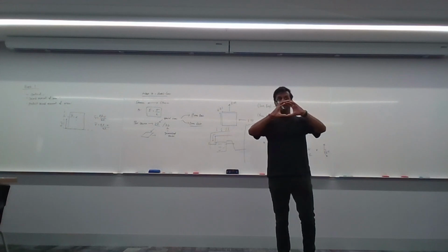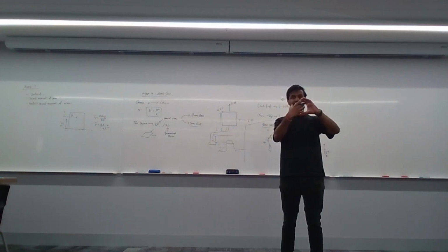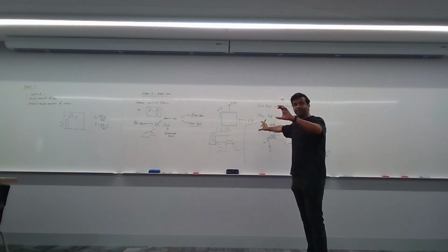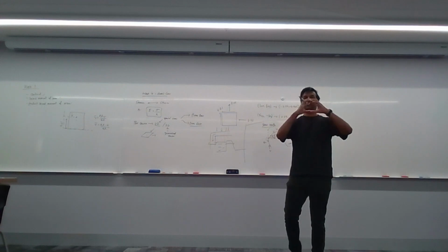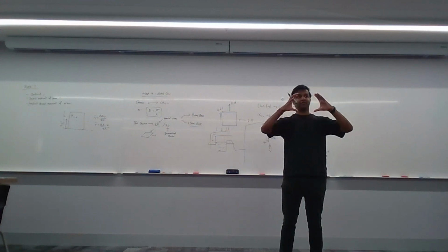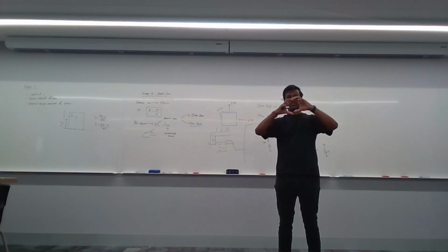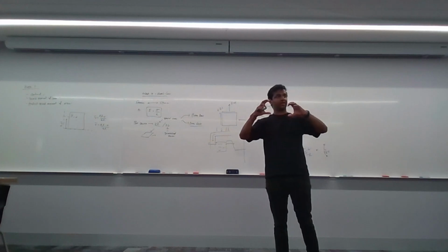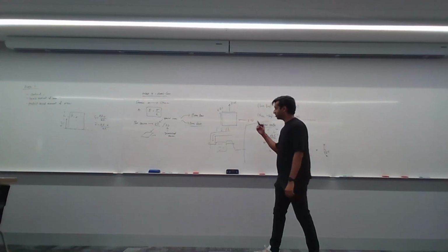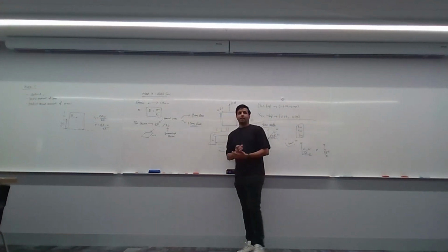Another example of plane strain would be a tube. If you've got a tube and it's full of water or pressure that's building up, but the tube runs into the board forever, so it's like a hose or something, and then you spray high pressure water through it. What will happen is the hose will want to expand outwards, but that's it. It won't expand into the page because that distance is super long. It just pushes outwards. Hydrostatic pressure pushes outwards. So that is also plane strain. So just remember that plane strain.